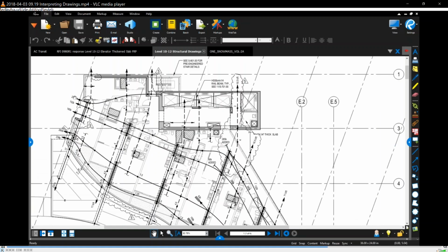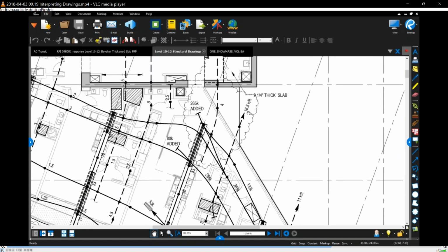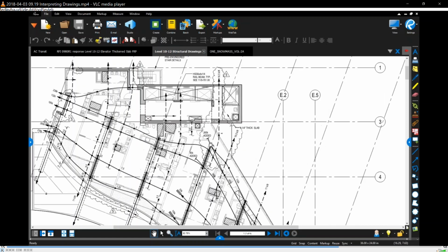So you see the 238 kips, that's a banded group of cables that run this way, 132 is this group, 185 kips is this group, and then these are called out 16 kips per foot. So that's your sign to what cables are uniform, if they have kips per foot, and what cables are banded as a total kip. So you provide a whole number of cables for that particular band.